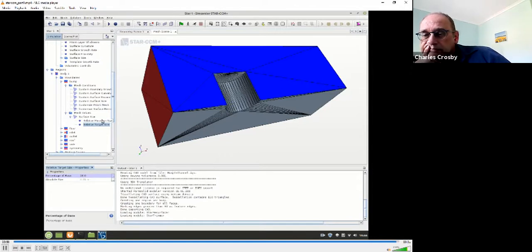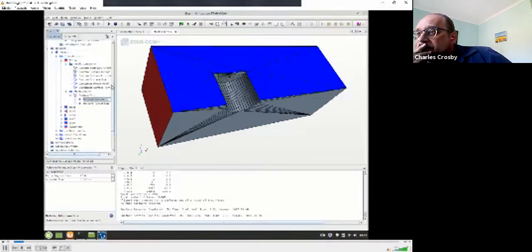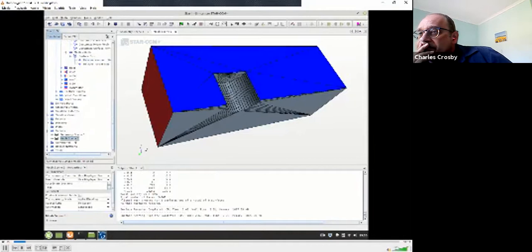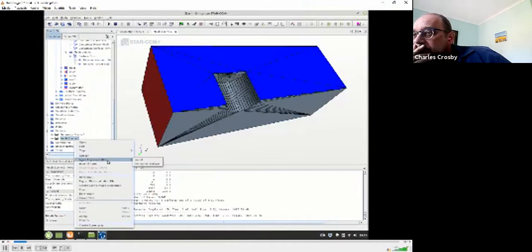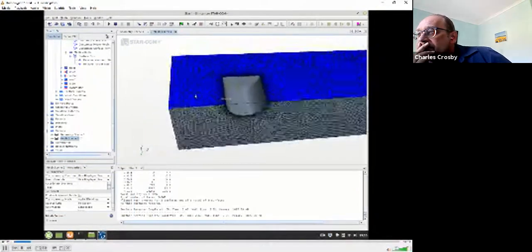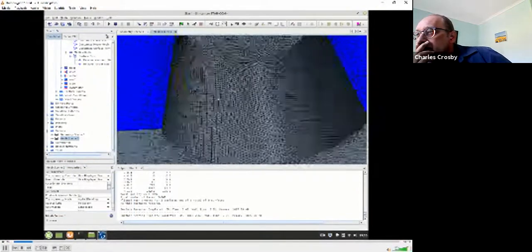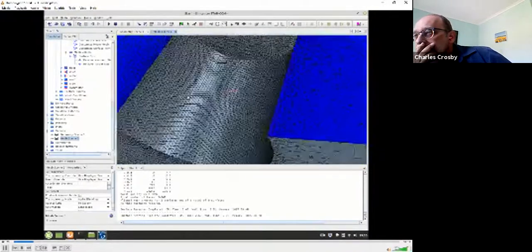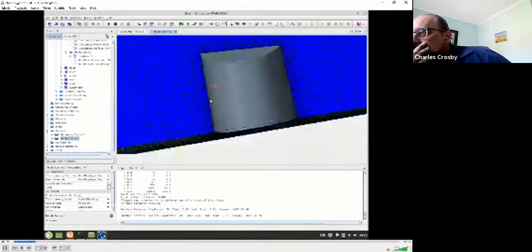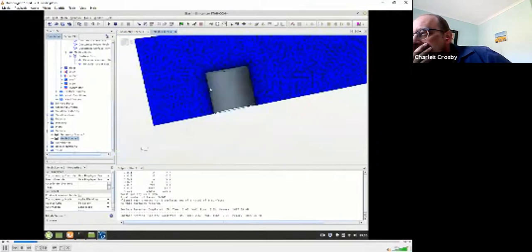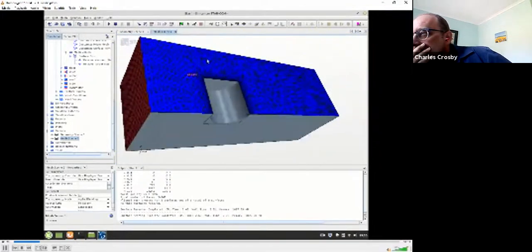We're now ready to remesh the surfaces. So from the mesh menu, we can generate a surface mesh. That happens very quickly because it's a very simple model. And if we go to our mesh scene, we apply the representation no longer of the imported mesh, but of the remeshed surface. So you can immediately see it is still a triangular surface mesh, but it's of a much higher quality. It's very smooth, and it's isosceles triangles more or less everywhere.